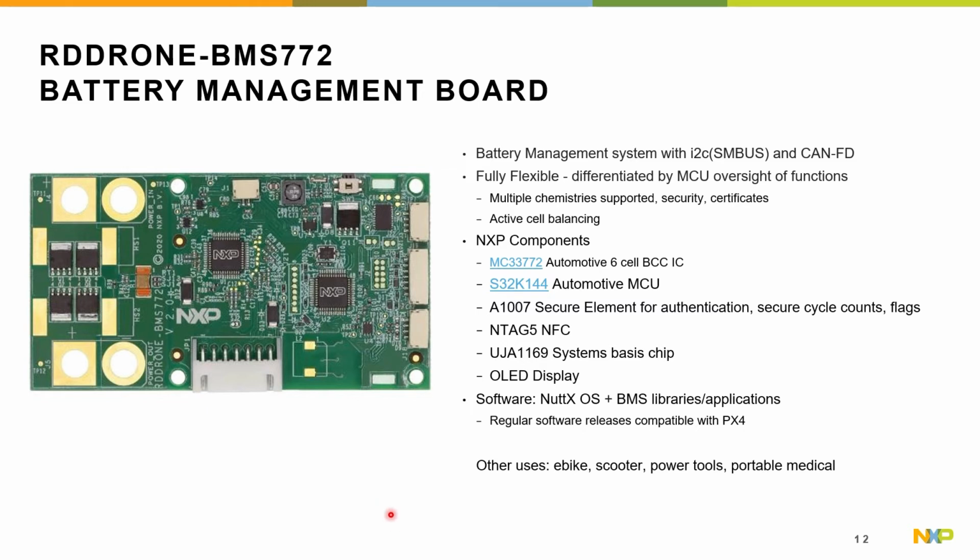And we have provided software, and we've been doing regular software releases that are compatible with PX4. So you have a console that lets you see state of charge, state of health, set parameters for different battery chemistries, etc. Really quite comprehensive battery management board.